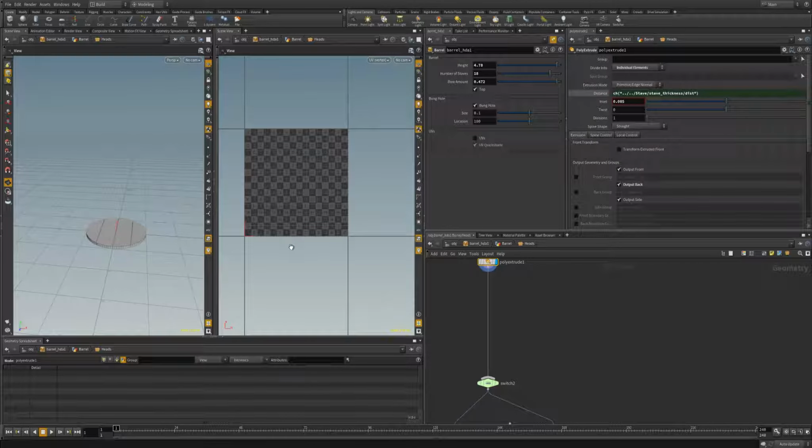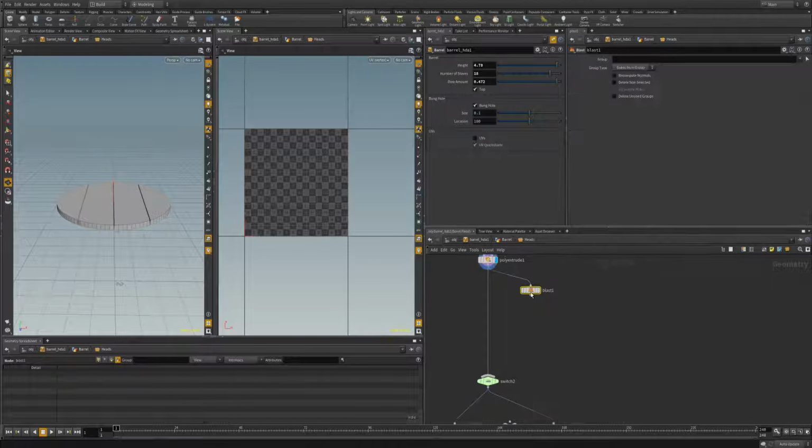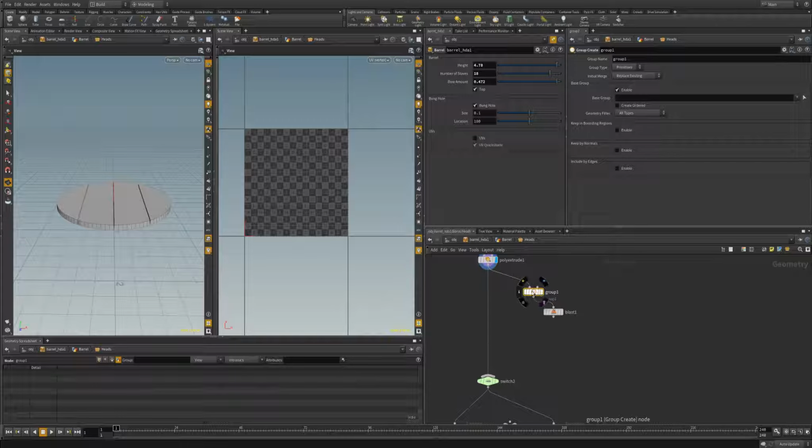And probably the best way to UV unwrap this, we'll maybe blast away the bottom primitive here, and we'll just flatten and smooth out the top. And we'll see how that works out. We may not even need to smooth out the top. So we'll grab a blast. Actually, let's group by normal. We'll be consistent, so I don't have to guess. And we'll call this the bottom faces group.